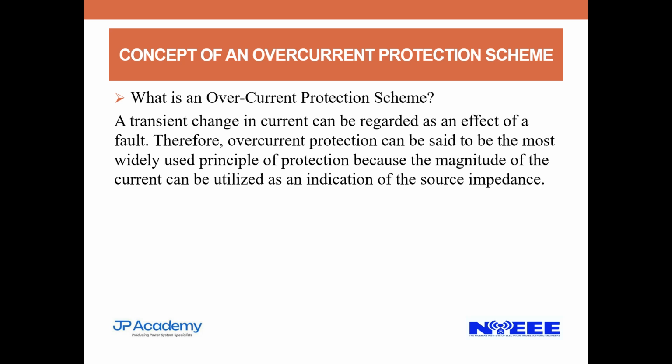So, an overcurrent relay, current transformer, and then a circuit breaker. Now, the protective relay is the one actuating the circuit breaker. The circuit breaker will be interlocked to the protective relay, and then the current transformer is used to measure and compare: what's the current flowing here?